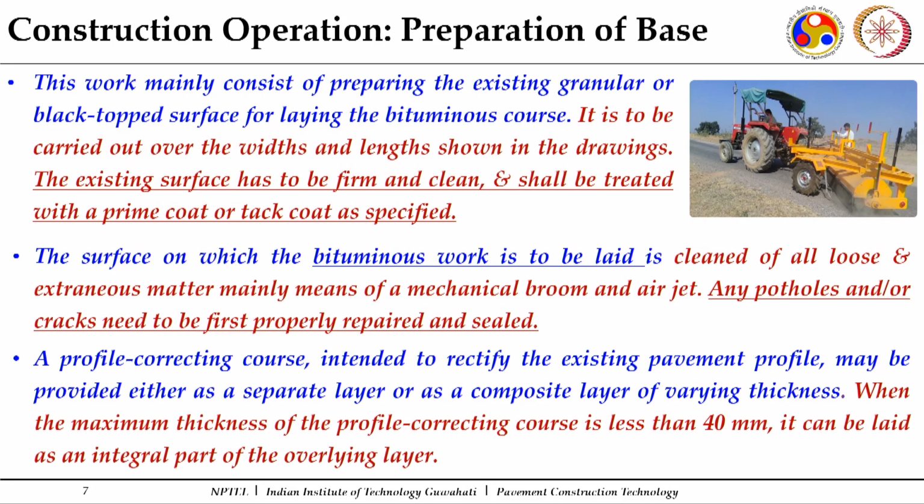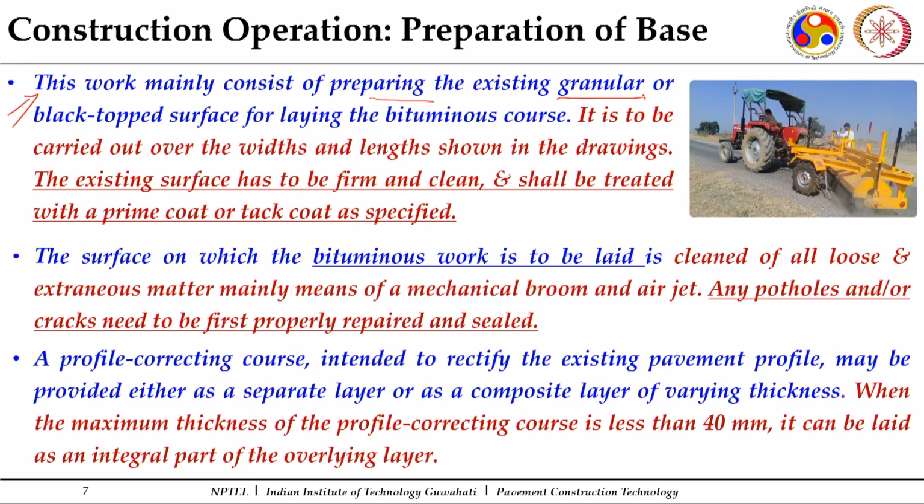Now, when it comes to the preparation of the base courses or the preparation of the existing ground to take up any bituminous bound course, it says this work mainly consists of preparing the existing granular, if it is a new construction basically, or if there is some major rehabilitation work, then granular courses can come. Otherwise, most probably in a new construction, definitely over the granular courses you will have to start with the bituminous bound courses. So, this work mainly consists of preparing the existing granular or blacktop surface for laying the bituminous course. Now, in new construction definitely granular courses, in some existing pavement, there may be a bituminous course existing.